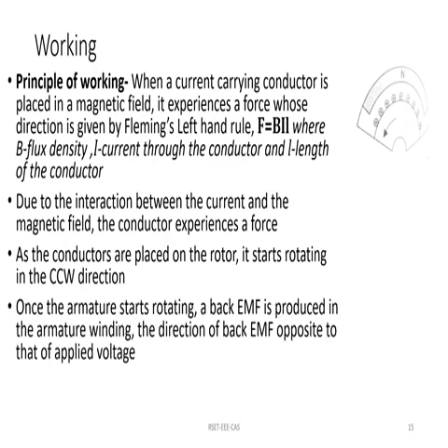Now once the armature starts rotating, a back EMF will be produced in the armature winding. Why? Because the conductors cut the magnetic flux produced by the stator field, and as a result an EMF will be induced, and that EMF is known as back EMF.